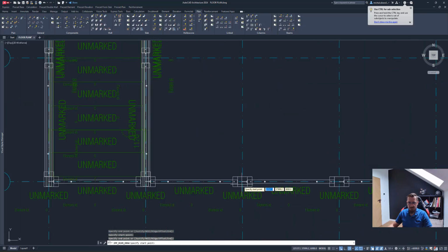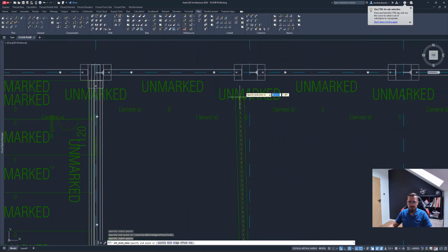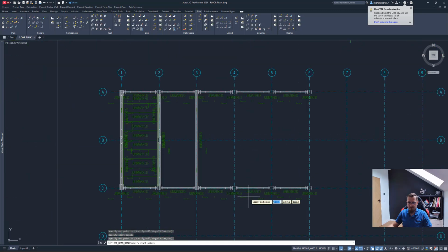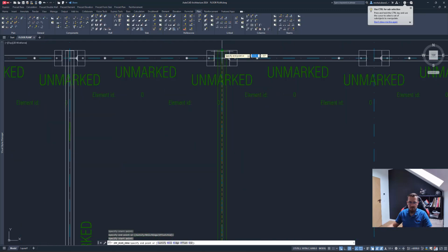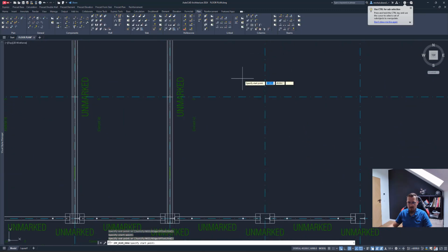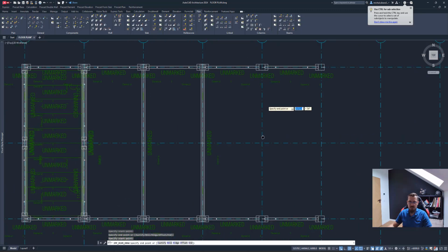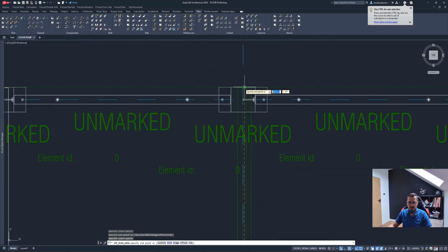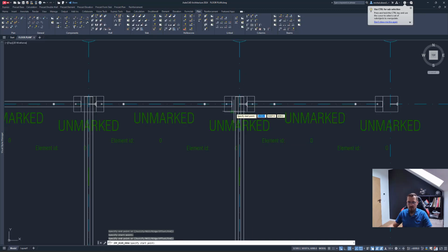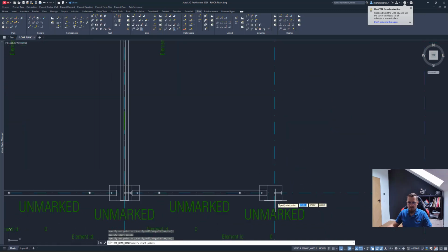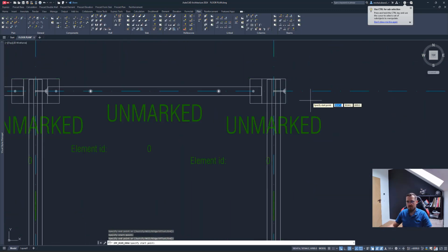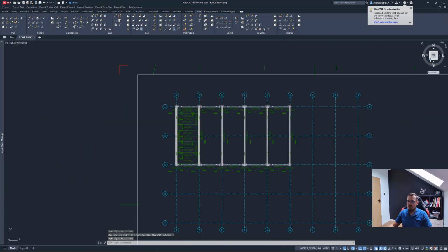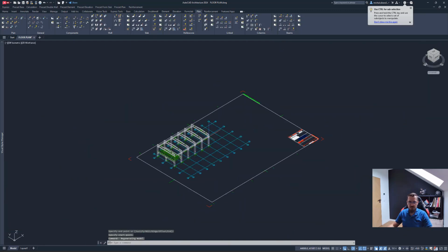Yep. Like that. The offsets are still applied from what I gather from the previous placement. If you would want those offsets, you would modify that with the O command now. Okay, and space to accept that. Let me go to this isometric view for you.